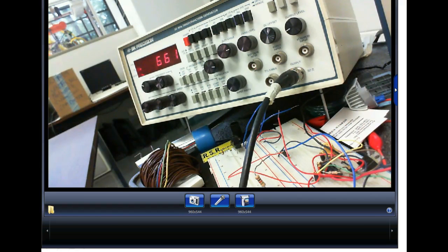So placing information on a carrier is called modulating. Stripping the carrier off is called demodulation. So we have these devices we hook up to our cable called a modem. What is a modem? It's a modulator demodulator. So when I put information on the cable, it places it on the carrier. When information comes into the modem, it strips the carrier off and lets the information come through. So we can modulate and demodulate with this guy.